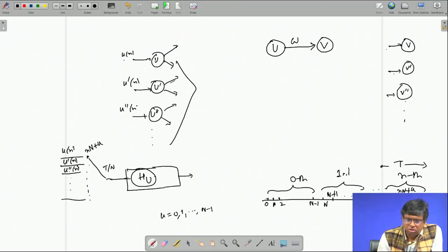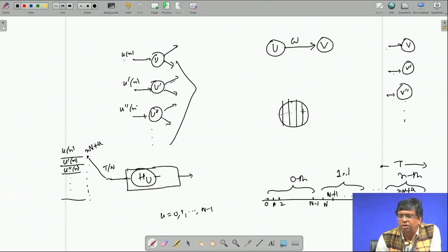So there will be some delays coming in, which means the output here will be a delayed version of the original output, because I am introducing delays in this hardware. The delays do the forward path retiming or pipelining. That is, this stage is divided into various stages, and between every two stages there will be a delay. So data coming here will not appear here in the same cycle; it will go through various delays and appear after some number of cycles.